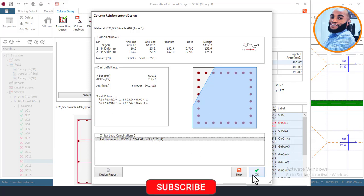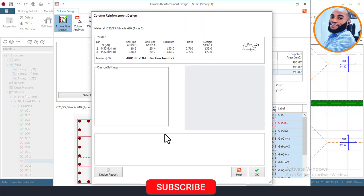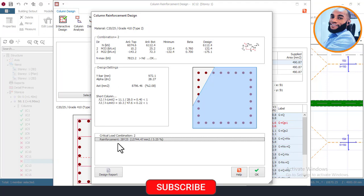So right now you can see the width of that column before was 600. That was not able to carry the weight coming to that column. So we have now increased it to 650, and we have checked that again and it's okay. As you can see, it is showing the bar quantity and the bar size. So with this, this column now looks okay.